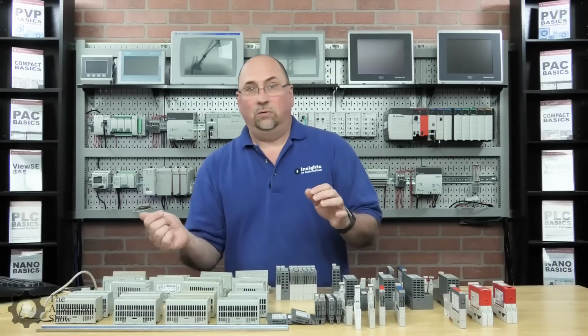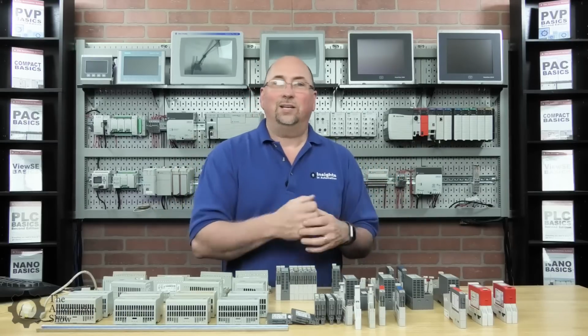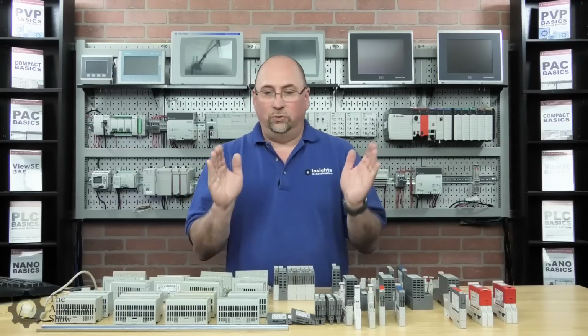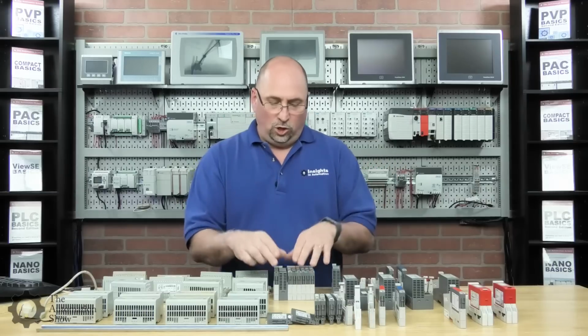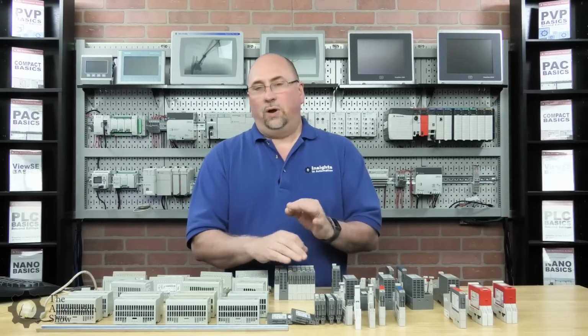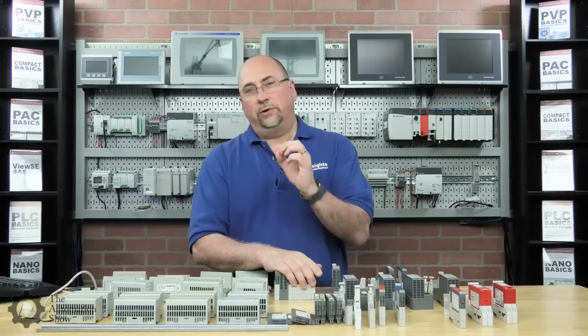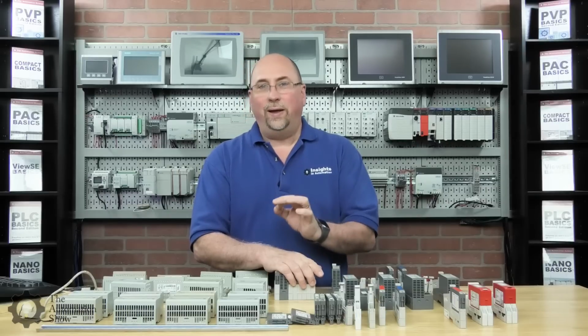Well, if the connection between the PLC and the I/O gets disconnected, you want that to keep doing what it's doing. It's doing a very important job. It's pulling out dangerous gas or liquid from an environment that could be harmful to people, right? So we don't want it just to stop because the connection to the PLC gets disconnected. If those fans or pumps are on, we want them to stay on, right? So not all of Rockwell's I/O will honor that last state setting when a user downloads to the controller.